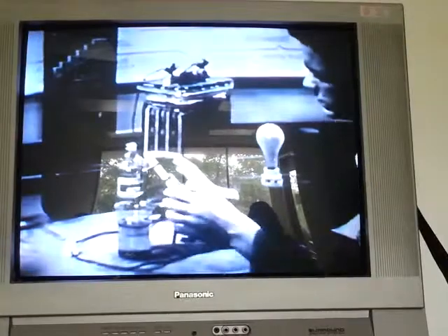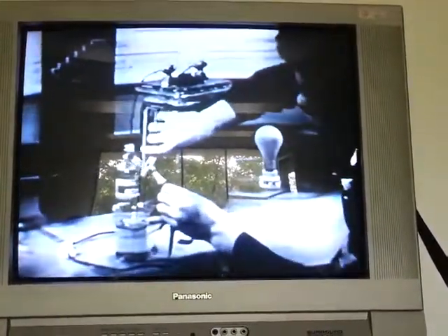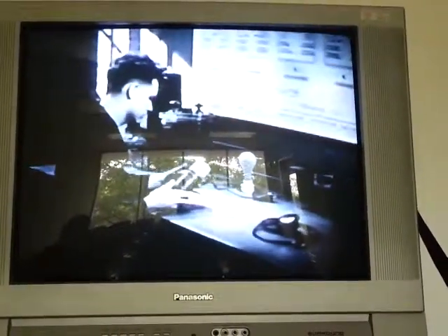The zinc dissolves in the sulfuric acid solution, which is called the electrolyte. Any cell which can be renewed merely by the replacement of the used-up metal electrode, or the electrolyte, is called a primary cell. The cells discussed so far are wet cells and contain liquids which limit their portability. The most convenient kind of primary cell is the so-called dry cell, which is actually a kind of wet cell with the moisture sealed inside its zinc electrode.